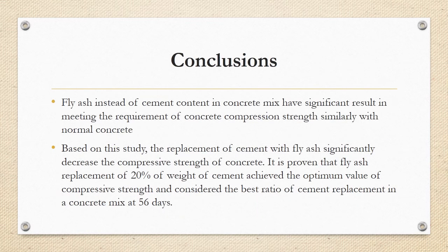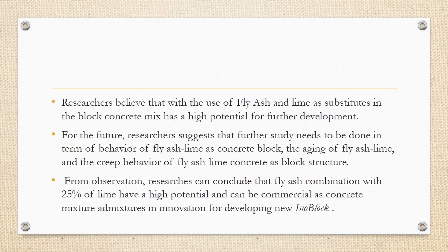As the conclusion, fly ash instead of cement content in concrete mix has a significant result in meeting the requirement of concrete compression strength, similar to normal concrete. Based on this study, the replacement of cement with fly ash significantly decreased the compressive strength of concrete. It is proven that fly ash replacement of 20% of weight of cement achieved the optimum value of compressive strength and is considered the best ratio of cement replacement in a concrete mix at 56 days.